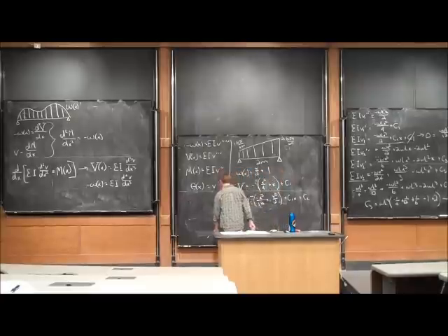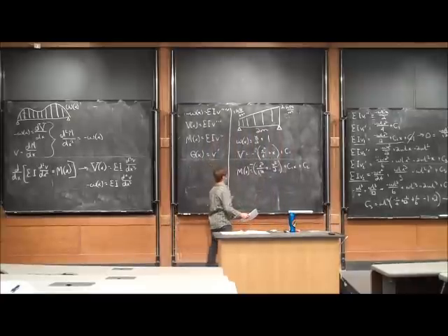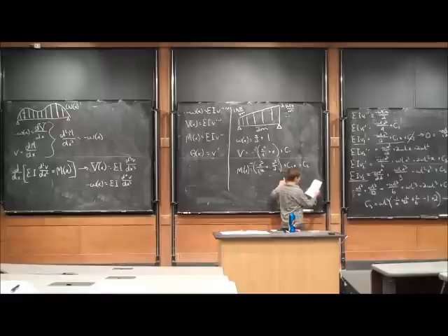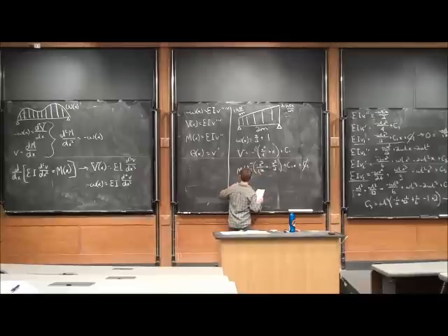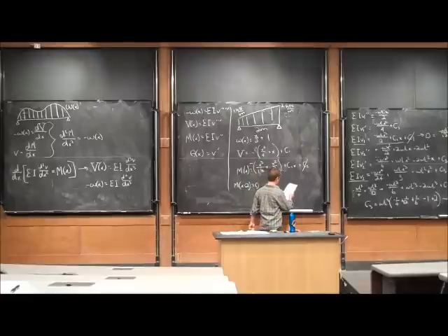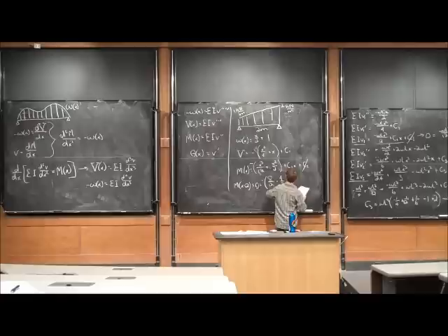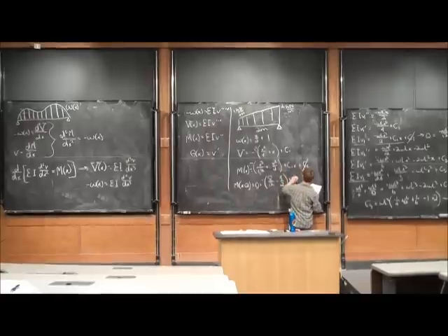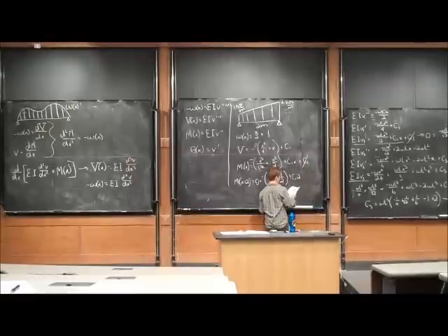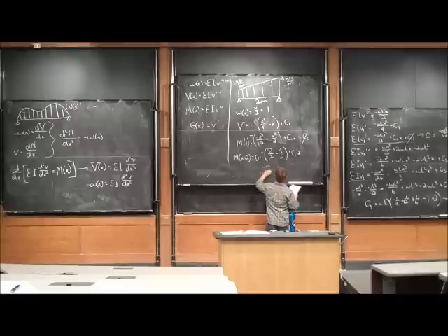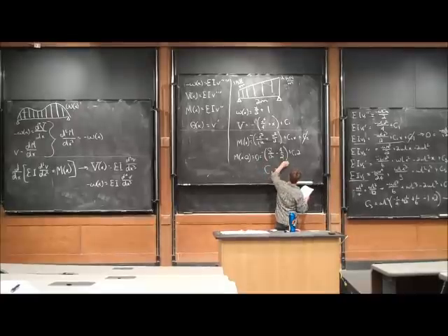So I can apply my boundary conditions at x is equal to 0. I know that the moment is equal to 0. That makes C2 go away. And I know that M at x is equal to 2 is going to be equal to 0, and I can plug that in. That's going to be negative 2 cubed is 8 over 12 minus 4 over 2 plus C1 equals 0. I can find that C1 is equal to 4/3.